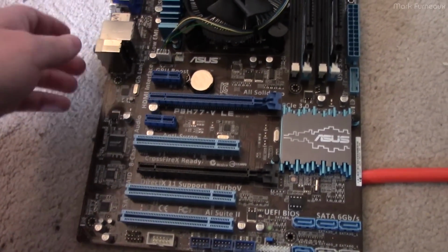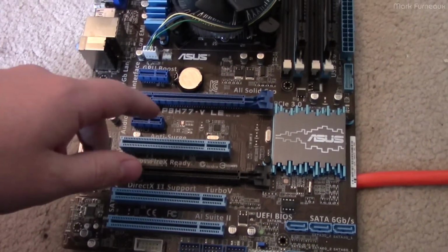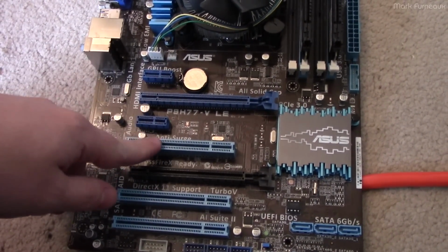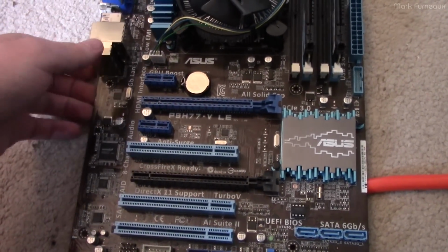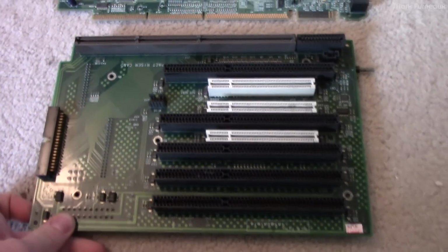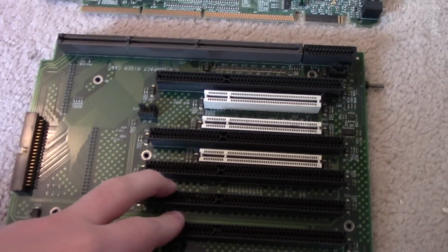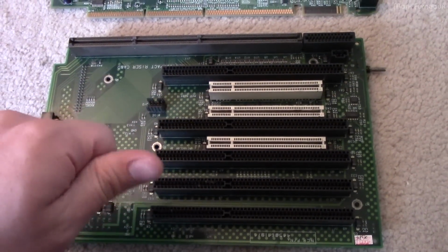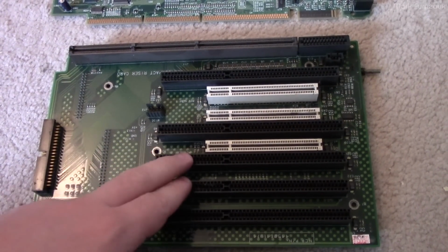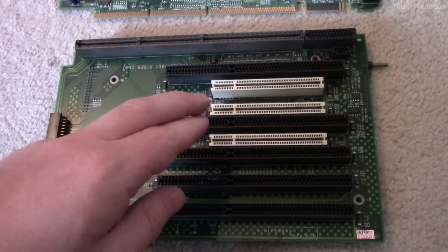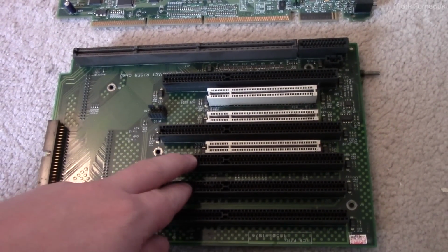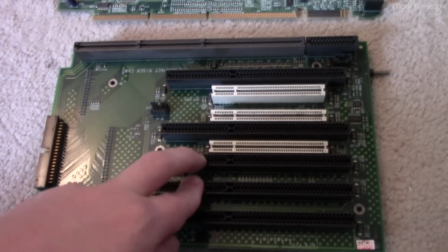But this is all great information, but this is for the opposite situation. This is where we have an old PCI device and want to plug it into a PCI Express slot. What about the opposite case, which is what we're dealing with on this old board? Well, this is one of the lesser known, cool things about PCI Express: when PCI Express was developed, they wrote into the specification that PCI to PCI Express bridges would be bidirectional.